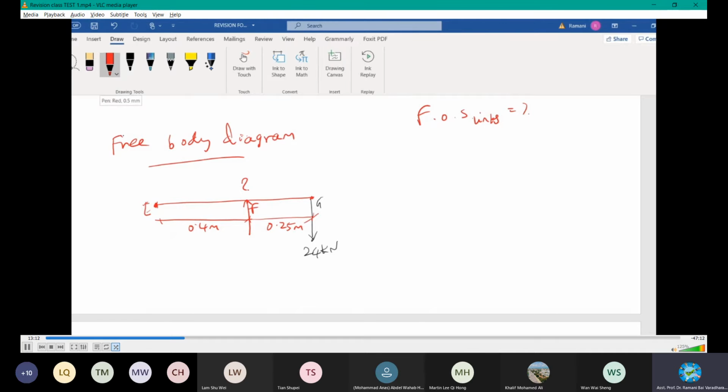Let's take the point E, okay? Resolve the moment about this point, section E. So when you resolve the moment about E, by equilibrium conditions, all the moment at ME should be equal to 0 because of pin joint. Taking this criteria, let's resolve all the moments about E.